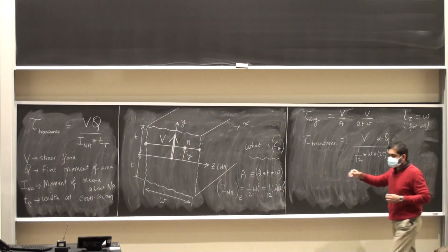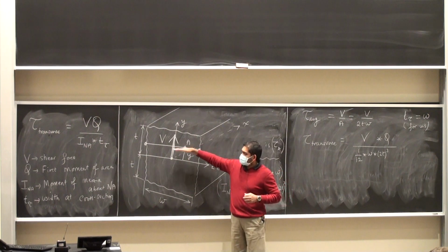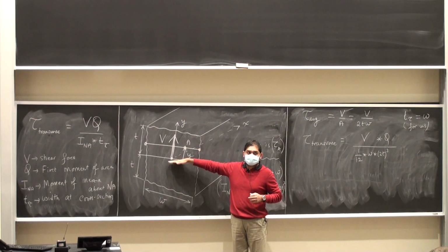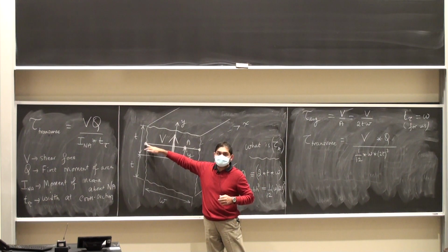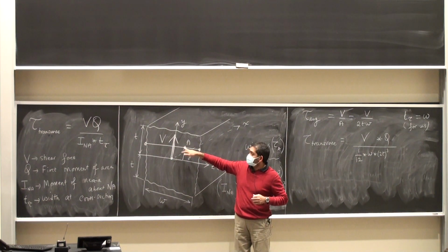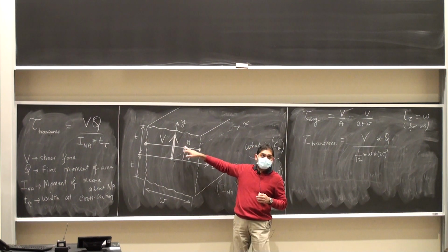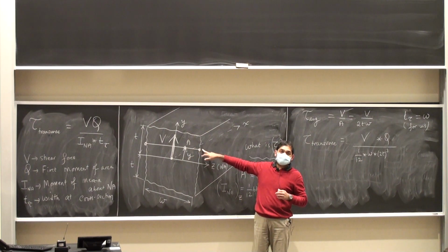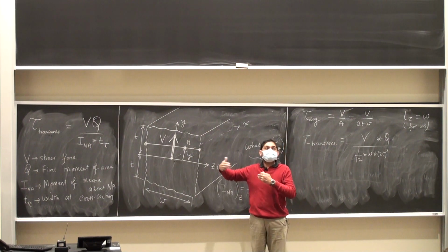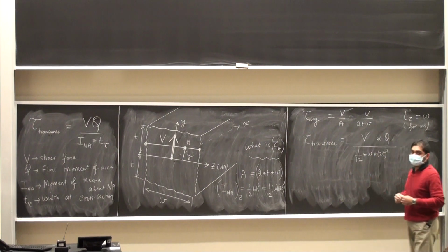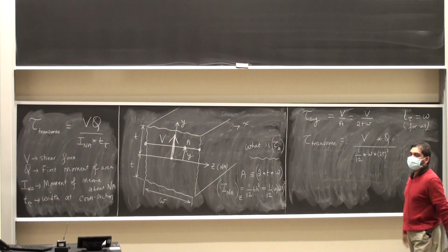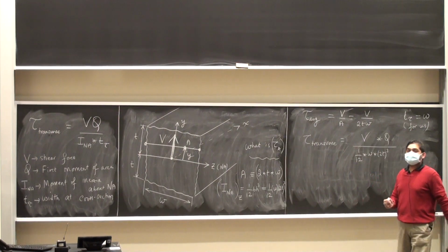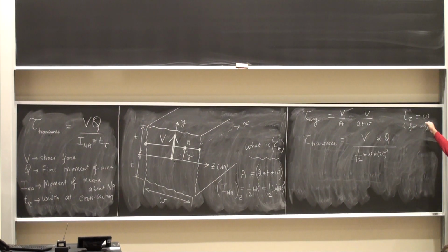Once again, draw a line parallel to the neutral axis. This line is going to start at one end of the cross section, intersect the points that you have chosen, and end at the other end of the cross section. The total width of this line is going to be W, t tau. Yes? So for all rectangular cross sections, it's going to be W, but for a circular cross section, it will be different. Absolutely. So this will be the same for all rectangular cross sections.